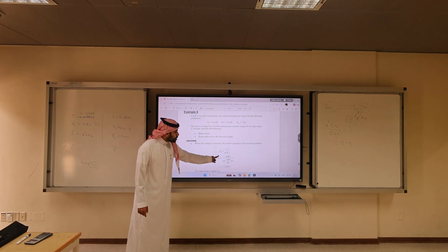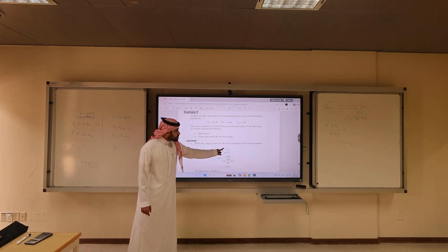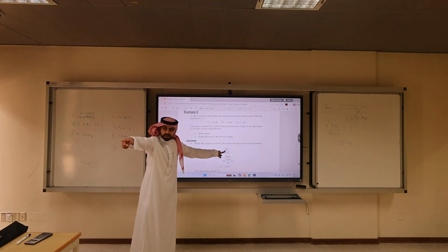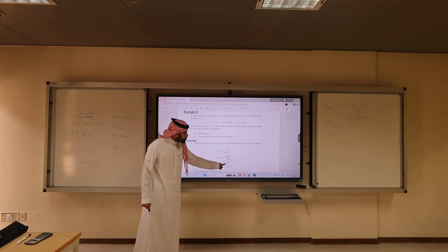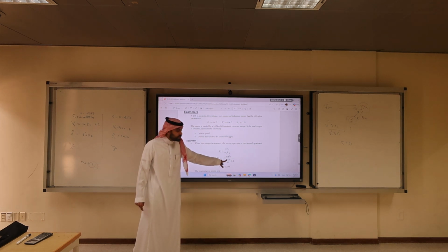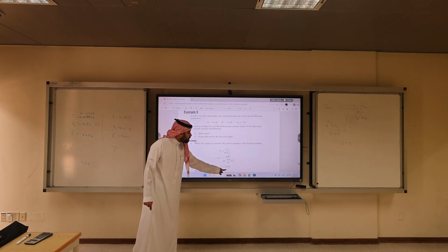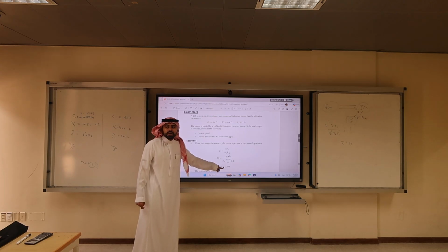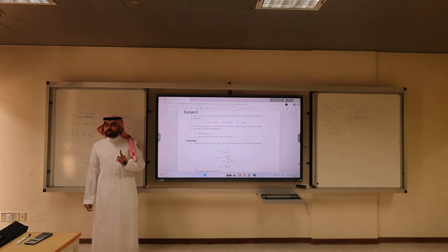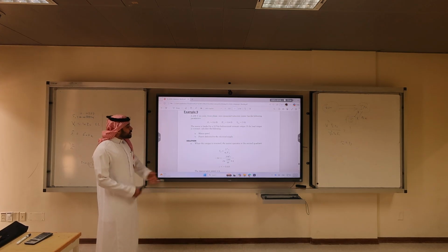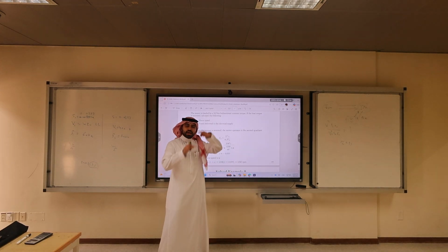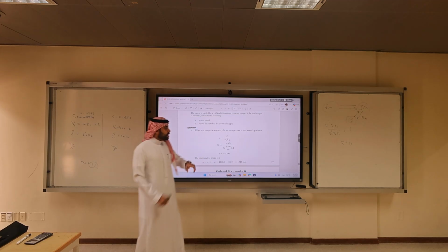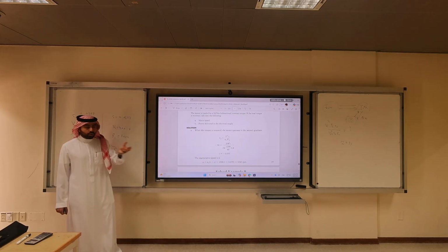Apply the negative torque. Use the approximation. Here there is no 3, so we use line to line. Is there a 3 here? No. So we use 208 squared times S times omega S, which is 2 pi times 1200 over 60, because synchronous speed for 6 pole is 1200, times R2 prime, which is 0.4, and you get the slip, which is what? Negative. What region are we in? We are in the regenerative braking. So the speed of the machine is 1242 RPM, higher than the 1200. So now we are in the induction generation mode, okay?